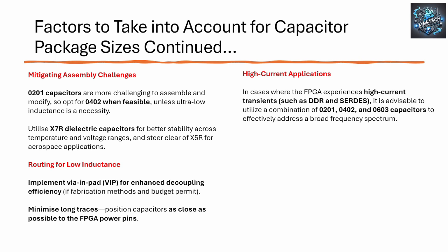If you're using a through-hole part, for instance, on an aerospace 2.4mm PCB thickness, we would use a typical 0.3, 0.6mm hole annulus via, or in freedom units, it'd be a 12/24 via. I'm talking thou now.